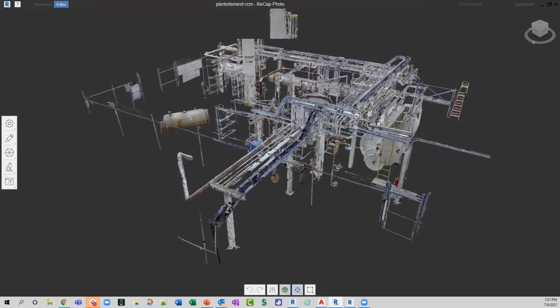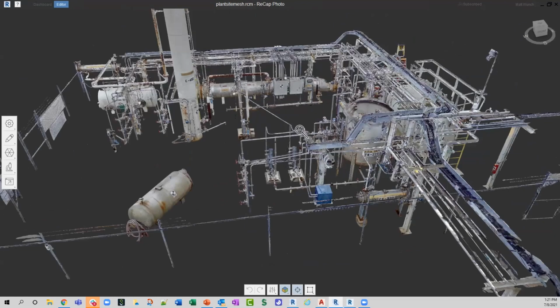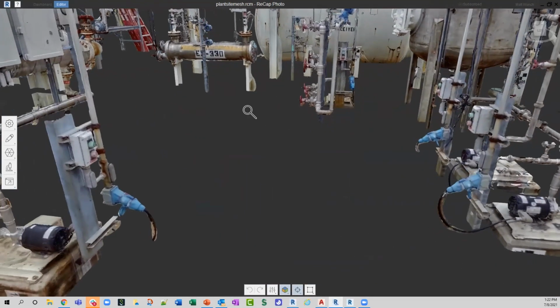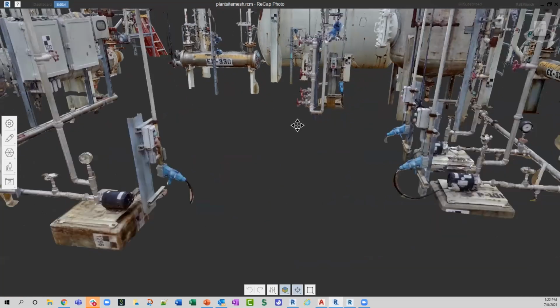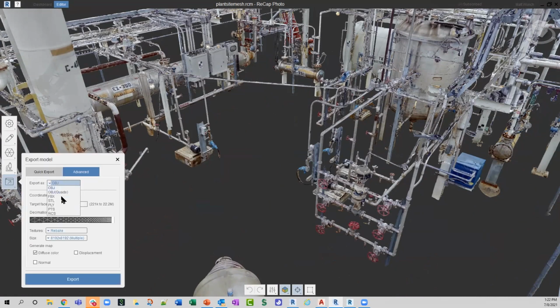This is that mesh from that plant site scan. And you can see, it does a really good job of recreating that 3D geometry based on the points, based on that 360 panoramic photo that's overlaid on top of each scan. And with the OBJ files, you can pull those directly into Inventor. There's also other options here to export to other file formats if you wanted to. Say FBX if you wanted to pull this into maybe InfraWorks or 3ds Max, you can certainly do that as well.